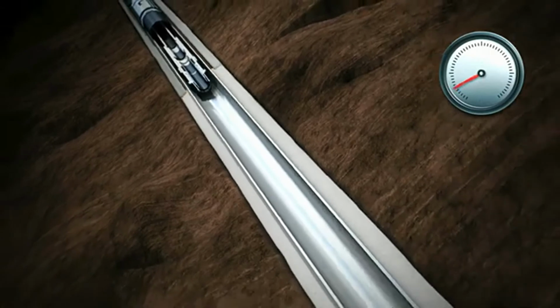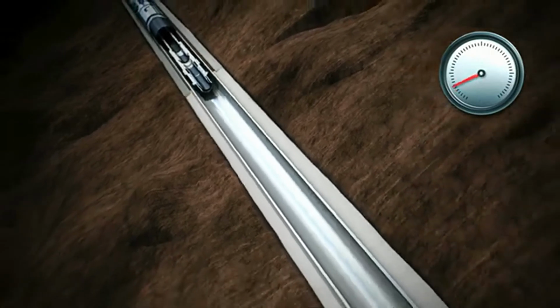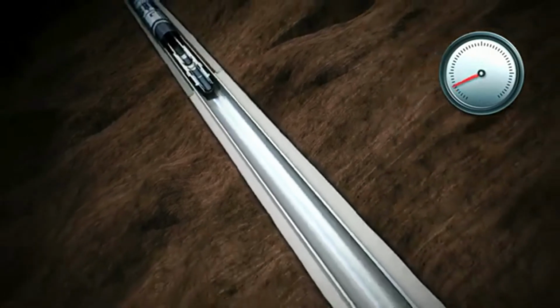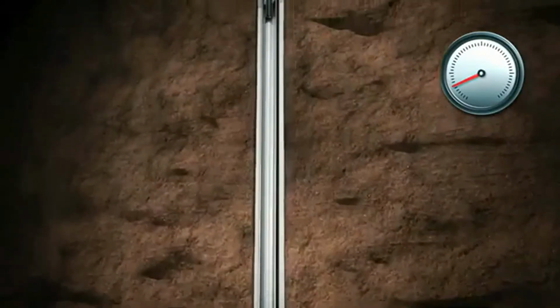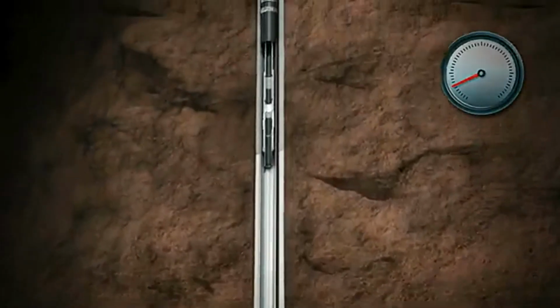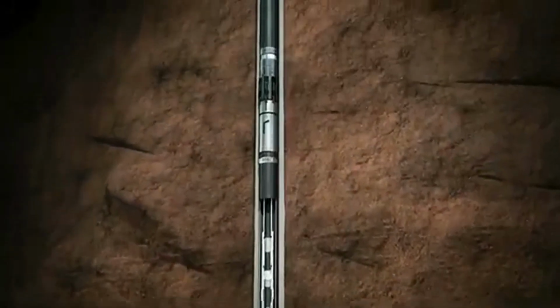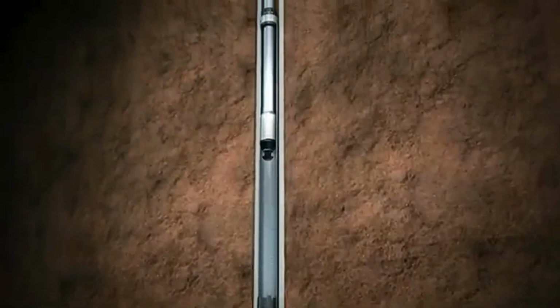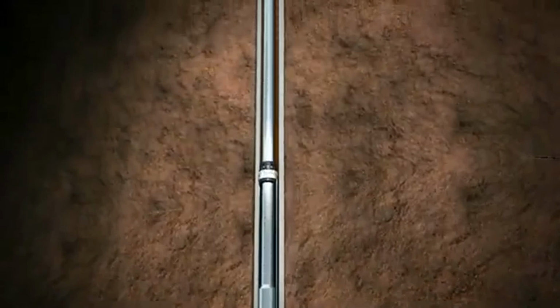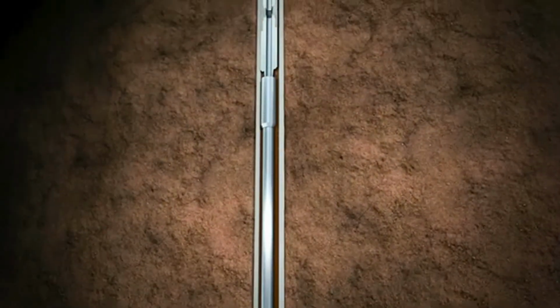After launching, the cement can finish displacing at an increased pump rate until the wiper plug assembly is bumped. After bumping the plug assembly, pump pressure is bled off to check float equipment, ensuring the floats are holding. This has been an overview of how surge reduction works in liner or subsea casing operation. Blackhawk equipment comes in various sizes and load capacities to handle any casing or liner sizes, ranging from 4.5 inches to 18 inches outer diameter.